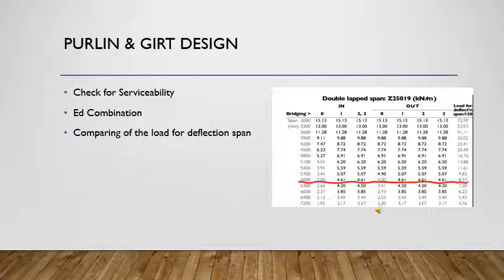According to wind span and Table 3.1 shape factors, suction and pressure, we can work out W for upward and downward. Then, according to Table C1 from AS 1170.0, the load combination can be selected. After that, from the side table, the load deflection span of the chosen section can be given. Now, we can determine whether or not the section can be selected by comparing.